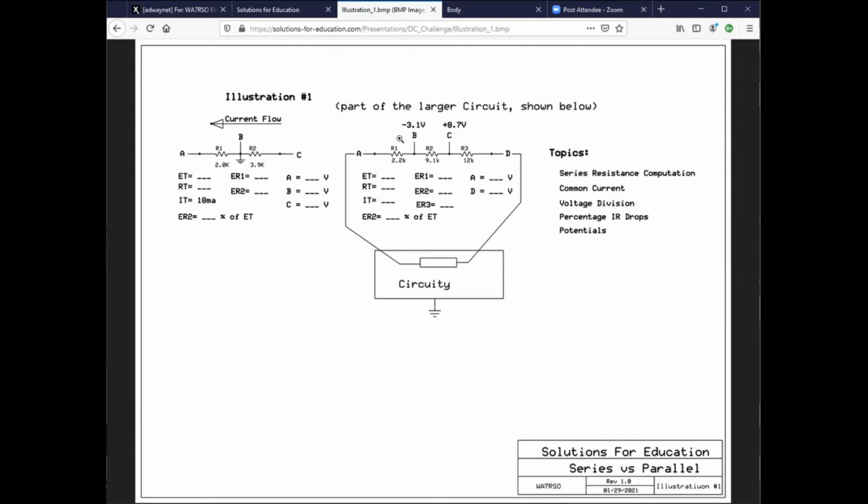All right, but if you have this voltage which is below ground and this voltage here which is above ground, that says there's about a 12 volt difference between those two. And that's the voltage across this resistor, which allows you therefore to compute the amount of current. But because this is negative, this is positive, that means current is flowing left to right in this drawing.